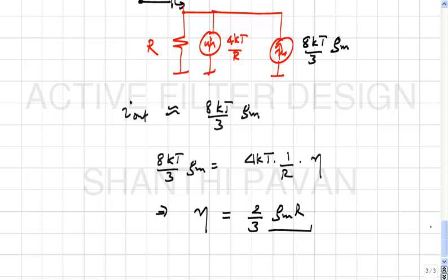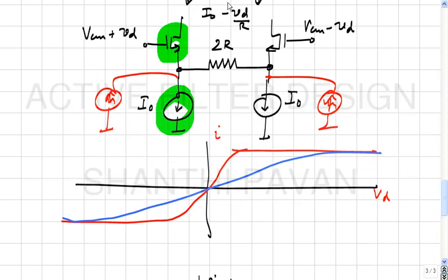Okay. Now one can argue that, hey, the problem is the noise due to this current source, right? Yes. Okay. So in principle I can improve the noise factor of this transconductor by reducing the noise due to this current source, which is equivalent to saying reducing the transconductance of the device that will be acting like the current source. But if I want a current I naught and if I want to reduce the transconductance, what does that mean? I must increase the overdrive. If I increase the overdrive, what happens to the headroom required? Decreases.